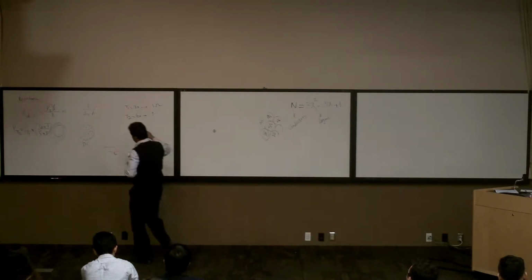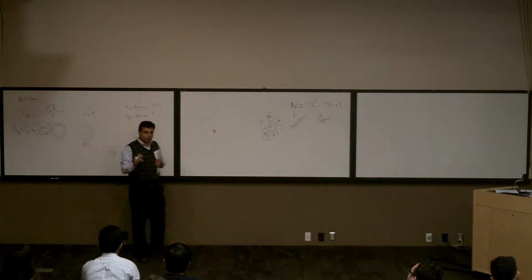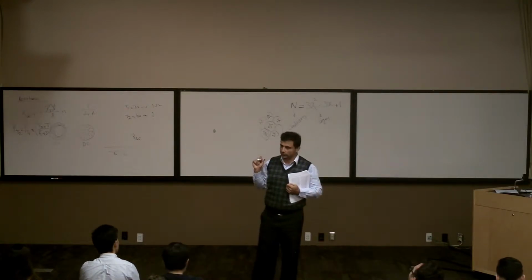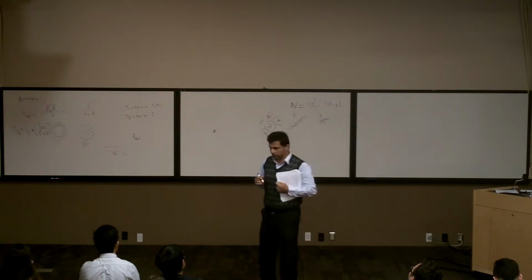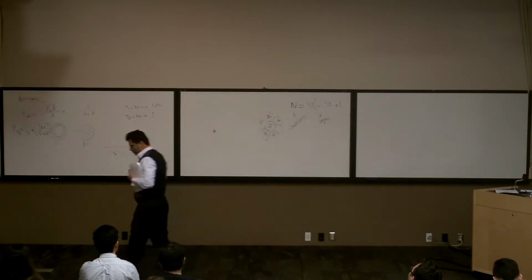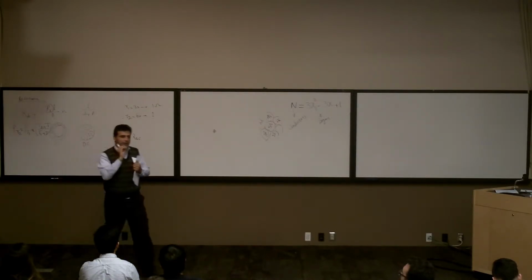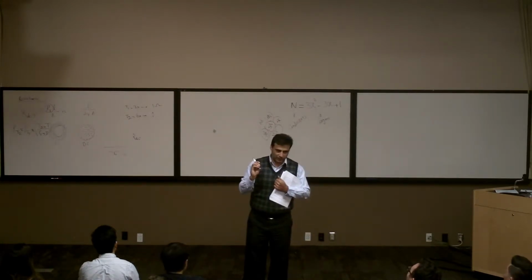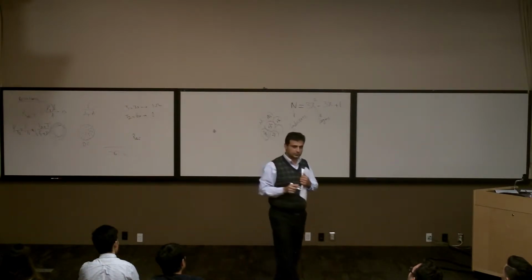And the last one is the skin effect, which doesn't affect the DC resistance, but it affects the AC value. Usually when the frequency goes very high, for example in power electronics, they go to 100 kilohertz switching. I may show you what I have from a simulation. You can see the current is going through the surface of the conductor, and in the middle there is no current. That is a bad thing. It's going to increase the power loss of the system. They call it the skin effect, or frequency effect.